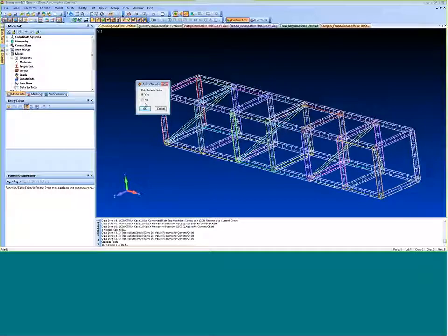Whereas if you choose no, it's going to make a property card for every single solid geometry you are creating a centerline for. And obviously, as the name implies, yes only works for tubular geometry, whereas no can work for everything: L-beams, I-beams, things like that. This model is all tubes, so I'm going to click yes.